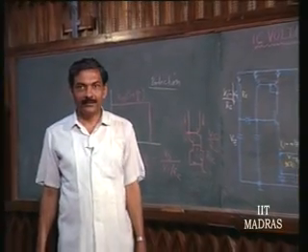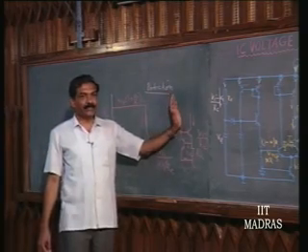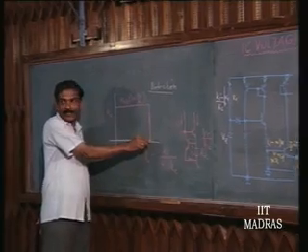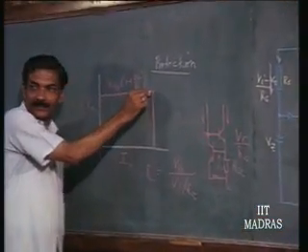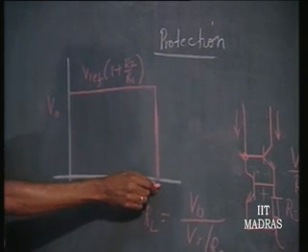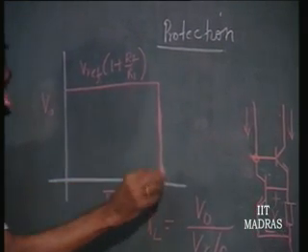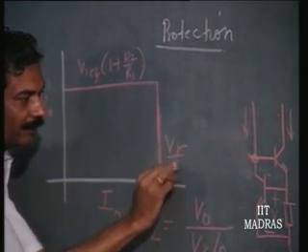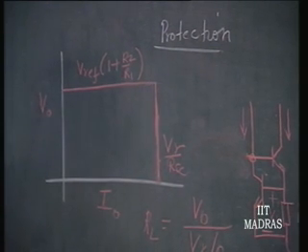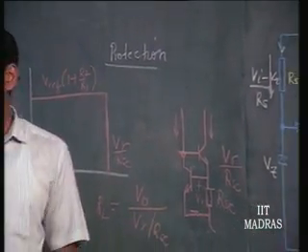So, this kind of limitation is now going to protect your circuit. Now, that is explained here graphically. This is the region where it is voltage regulator, and here you can sustain any output voltage. It is no longer voltage regulator, it is a current source of V gamma divided by RSC, constant current. So, this is the way we can protect.